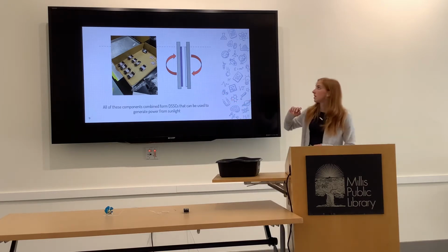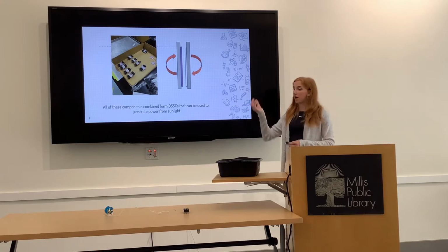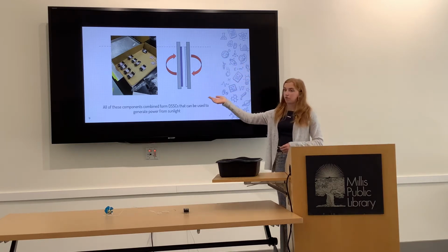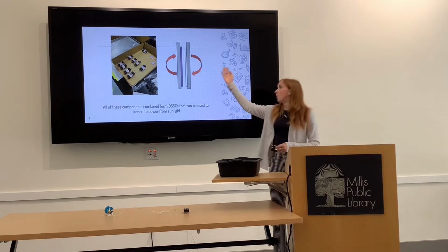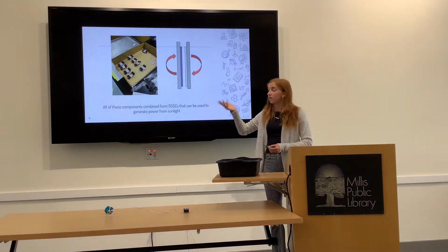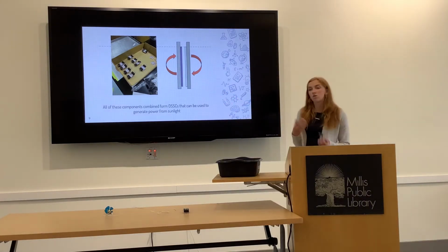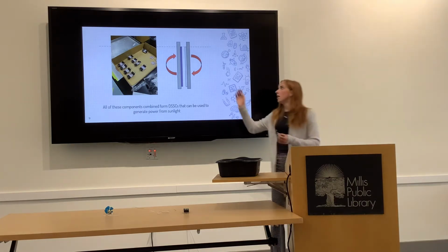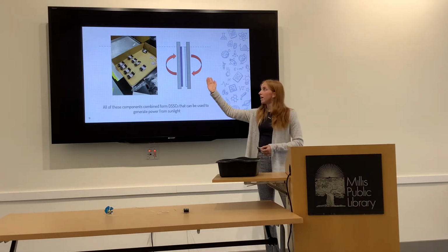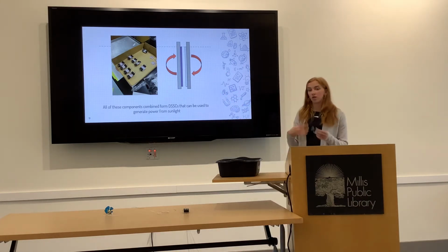So what happens is I would take electrolyte solution in a pipette, drop it into the solar cell, and once that electrolyte solution flows throughout the cell, it moves towards the titanium dioxide and the blackberry juice. Light comes in through that side of the cell, is absorbed by the blackberry juice, and gets those electrons of the electrolyte solution moving super fast and flowing around. Then they start to cycle through back towards the cathode, the pencil graphite, and are broken down, start moving slower again, and go back to their normal state.